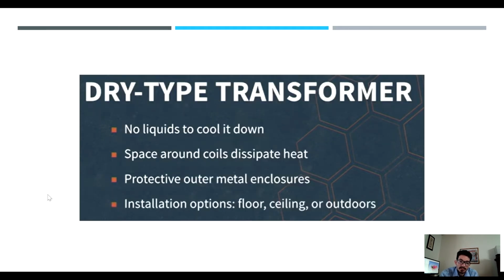There are different types of transformers. One of them is the dry type. The dry type is what you would find in a dishwasher because it's enclosed, right? The dishwasher uses water and high temperature steam, but that is inside the casing. You don't have those going to the electronics. In a refrigerator, you have a transformer in the control board that is also a dry type. Dry types are the ones that are enclosed, and we'll see pictures and figures in a little bit.